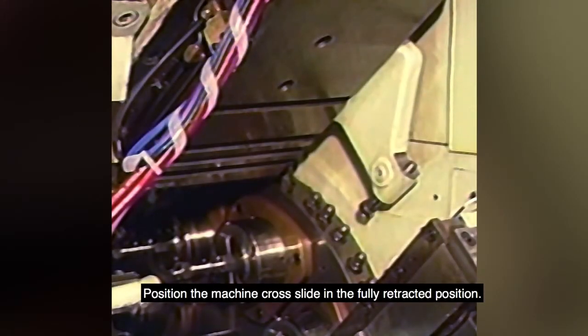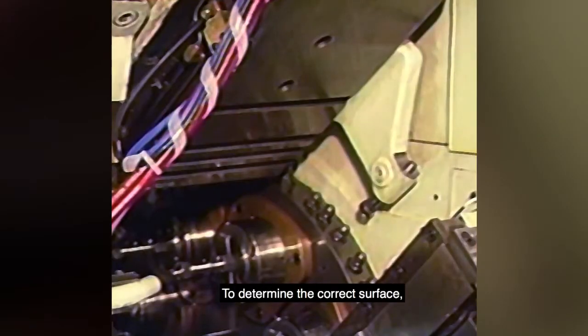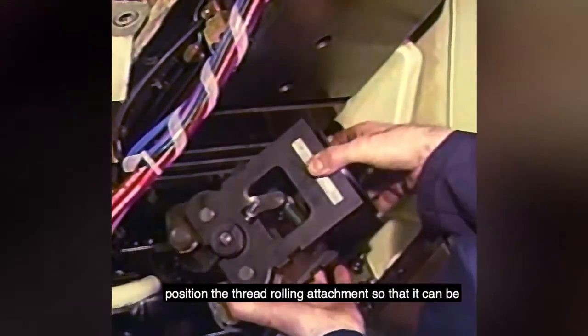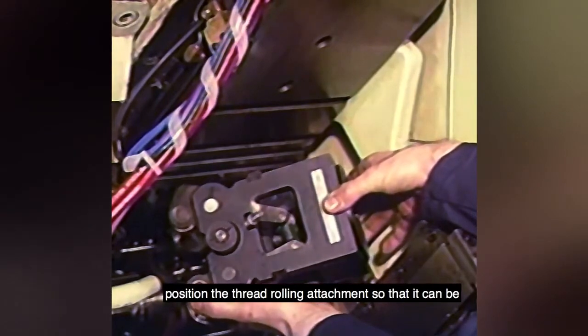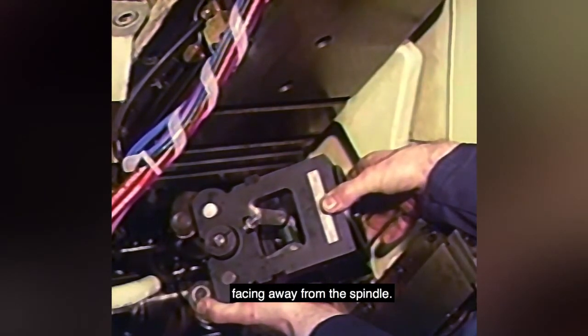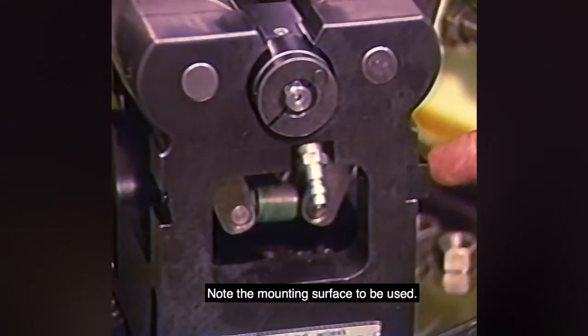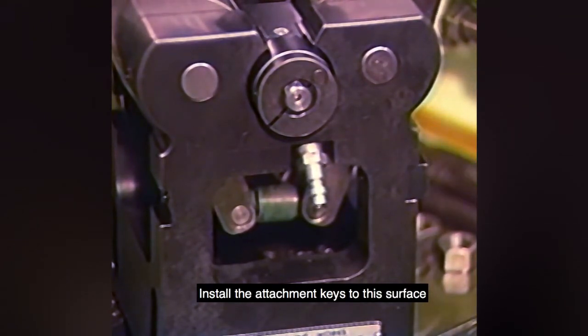Position the machine cross-slide in the fully retracted position. Note that the thread rolling attachment has two surfaces on which it can be mounted. To determine the correct surface, position the thread rolling attachment so that it can be installed on the cross-slide with the compensator assembly facing away from the spindle. Note the mounting surface to be used. Install the attachment keys to this surface using the hardware supplied.